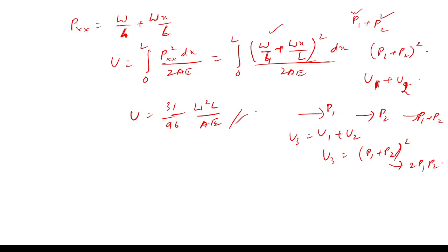Here the flange weight is the pure axial loading. Yes, the flange is a pure axial load because here they have asked the strain energy of a prismatic bar only. So when you take this prismatic bar, due to this you have self weight W plus you have one axial load, which is the weight of the flange, which is W by 4.